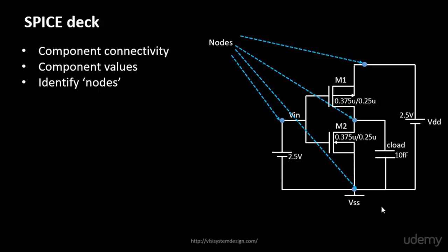Okay, let's pick up another component. For example, let's say we have this load capacitor. The load capacitor can be very well defined between this node and this node, because this is a node which is common to all of them, common to the VSS common node, and you have this particular node which is present at one of the parallel plate capacitor of your output load capacitor.